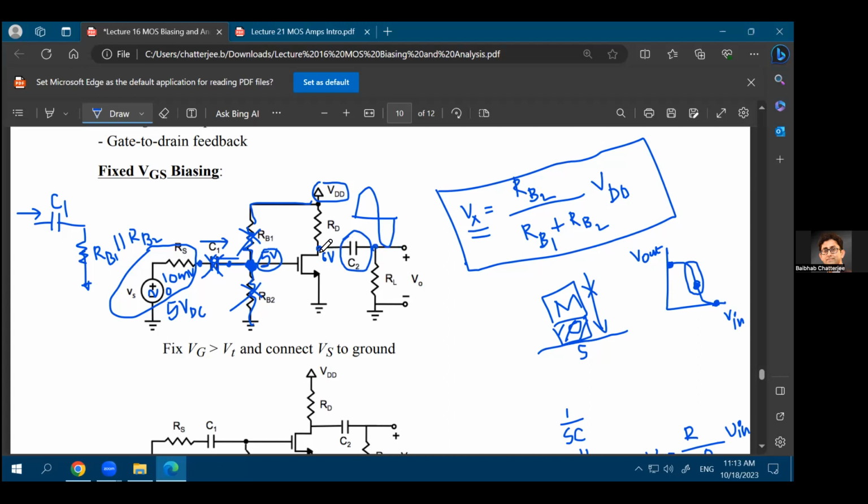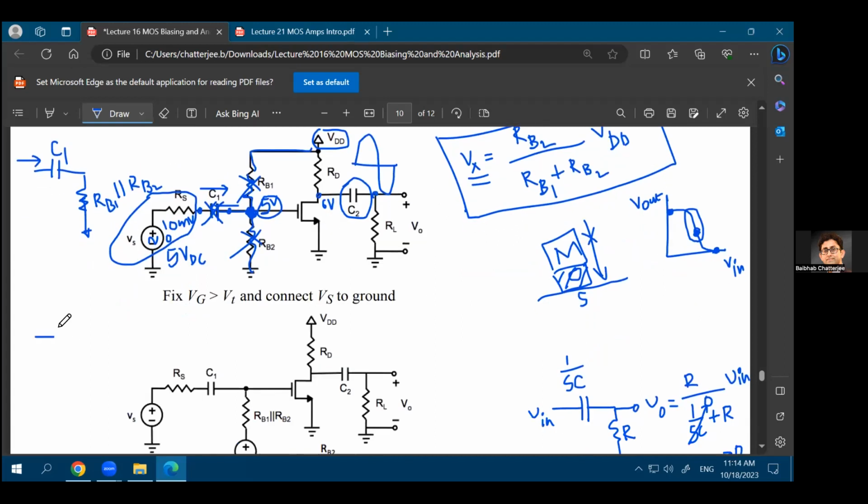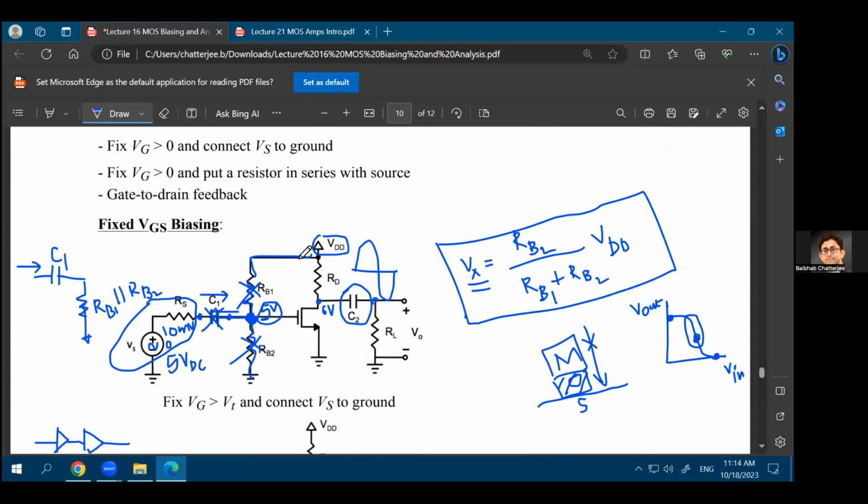So in this way, for example, let's say you have a 2-stage amplifier, this is your first stage, and again you are connecting the same stage at the output of the first stage. So you can just have 2 stages of amplifiers. You have also learned this in the beginning of our course, right? If you have 2 amplifiers back to back, and the first amplifier has a gain of 10, the second amplifier also has a gain of 10, the total gain you can expect is 100, 10 multiplied by 10. So you can just connect one amplifier after another, and in that case, this AC coupling really helps you a lot, because then your DC points are decoupled from each other.